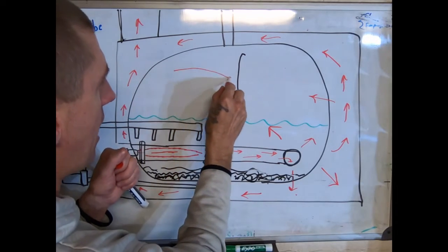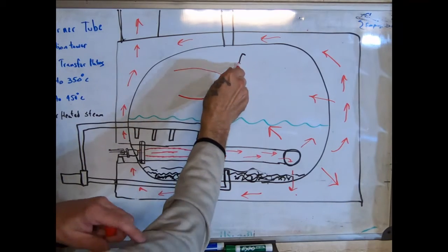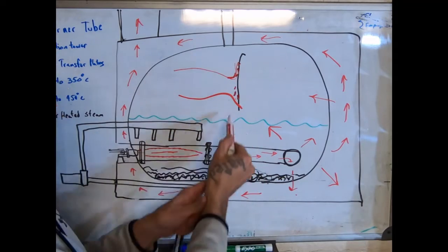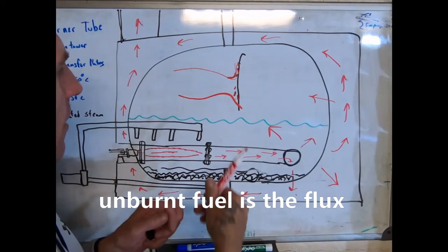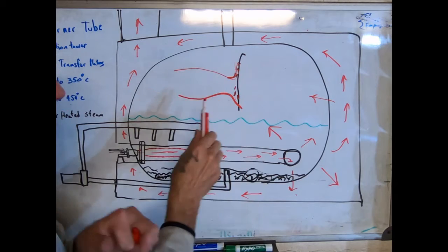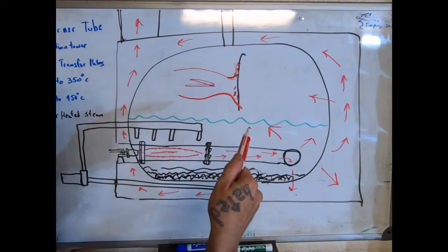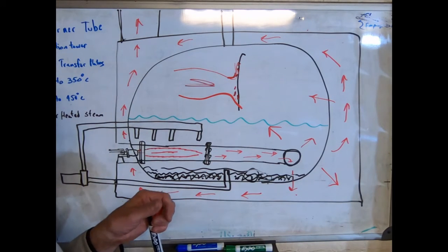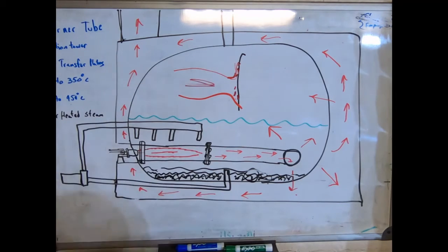So if you take a flame and you blast it right on there, what happens at this interface, the interaction between the flame and the metal, is a fluxing action that removes that oxide layer, exposing a continual new layer of metal that is eroded away by a high temperature and the fluxing action of the fuel. Not to mention the fire that we're aiming on this thing is a product of this distillation system that is a very high sulfur content fuel, which just totally adds to it, tenfold. That sulfur stuff is very corrosive.